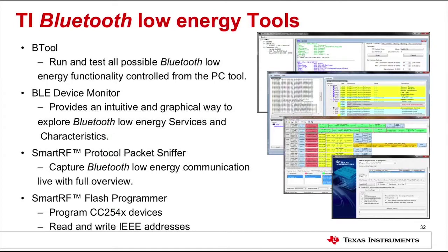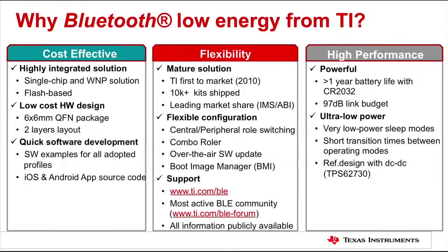There's also a SmartRF protocol packet sniffer. So this gives you a full overview to be able to capture the communication and see what's going on, see if you're seeing errors or different things like that. And then the last one is a flash programmer that allows you to program the devices itself and read and write addresses.